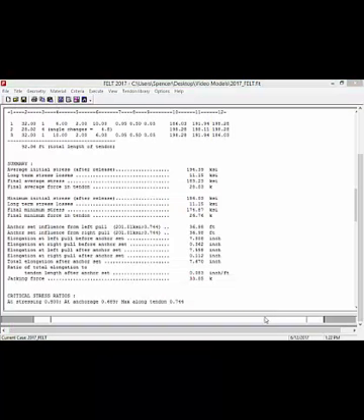In the detailed output, the program reports the ratio of total elongation to the tendon length after anchor set. In previous versions of the program, the total tendon length was the projected length of the tendon. In version 2017, the total tendon length accounts for the curvature both in plane and out of plane for the tendon.